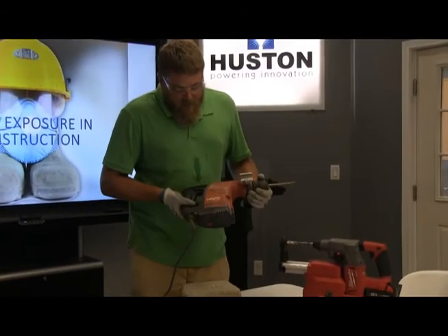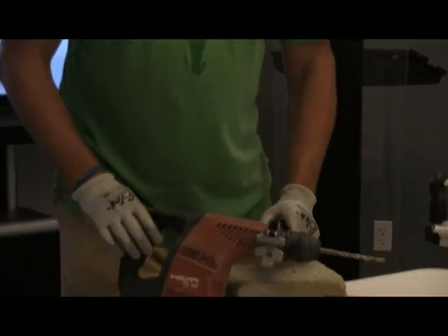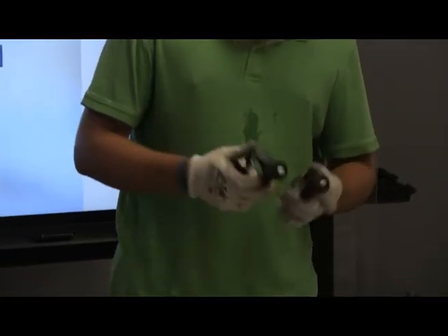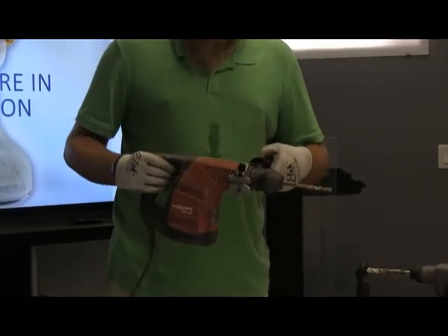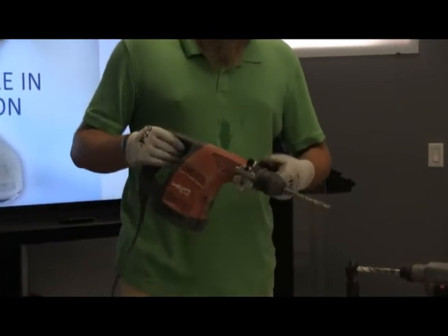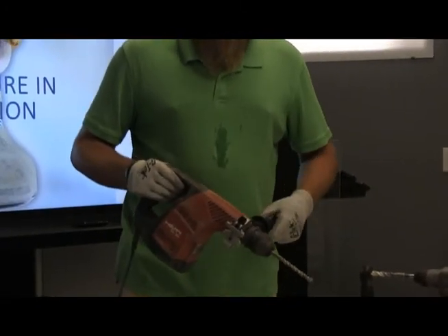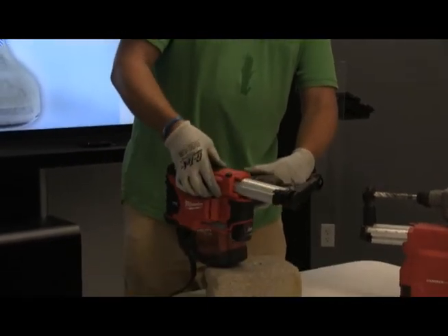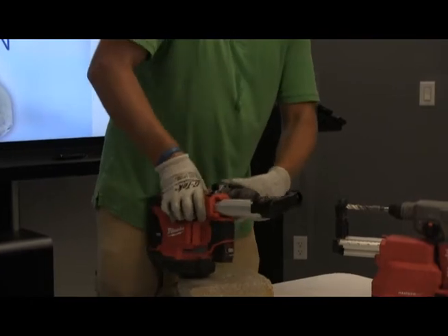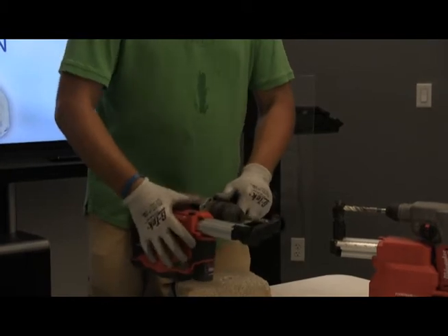So this is a Hilti T30. In order to install these, all you have to do is, in the M12 kit, there are 3 different size collars: small, medium, and large. So you pick out the collar that fits, and I think this is the medium size collar that I put on this one. You literally just put it on, tighten the handle, the collar tightens around that, and then this simply just clamps onto the outside. Once again, you make sure that your bit is through there, and it literally just clamps on just like that.